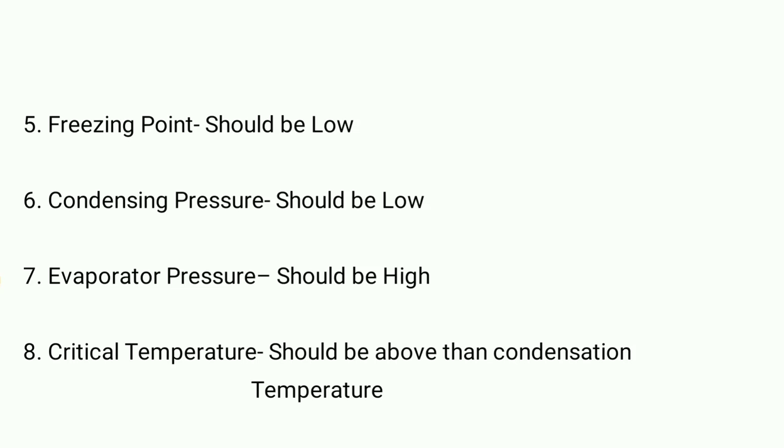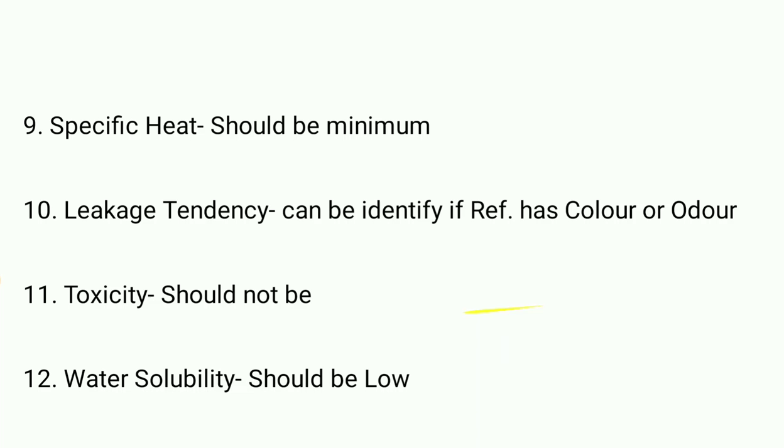Then freezing point should be low. Condensing pressure should be low. Evaporative pressure should be high. And critical temperature should be above the condensation temperature. Then specific heat should be minimum.